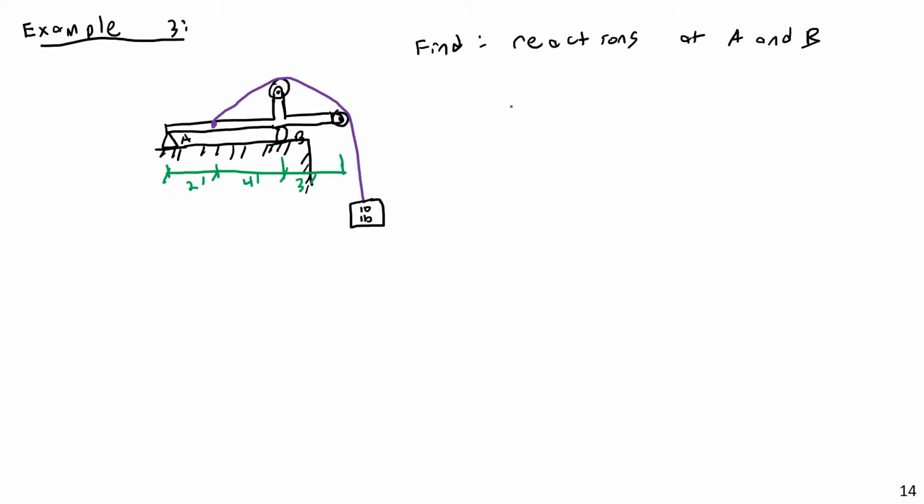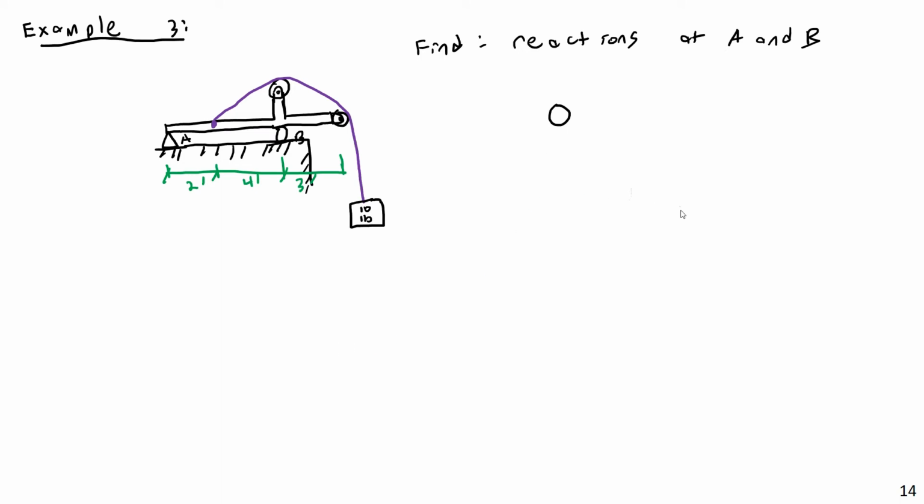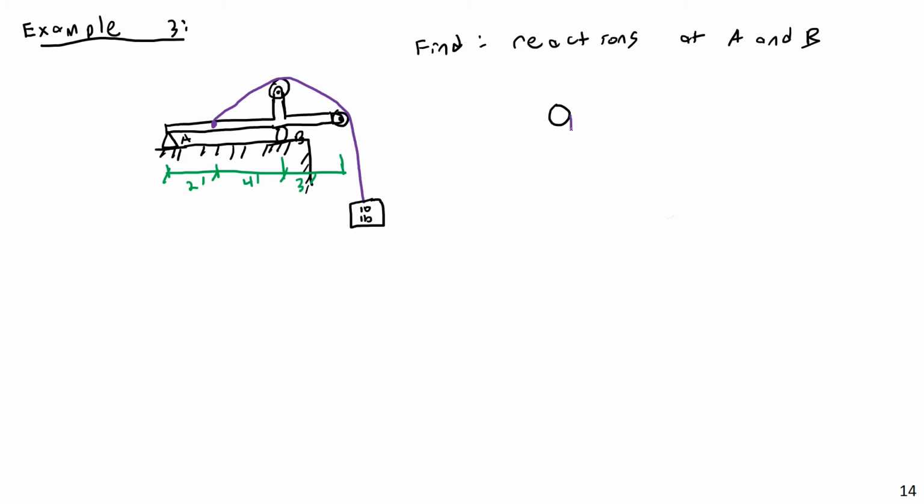And think about how the tricky part is actually this location here. If you think about that pulley, that rope is not going to be able to generate any kind of vertical force at the edge right here. The rope's going to come here and then immediately pull around. So it may be able to exert a force like this, but it's not going to be able to exert a downward force once it passes the midline of the pulley. But it will be able to exert a force like this.